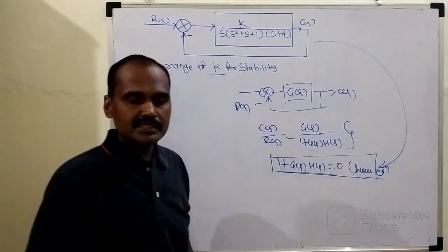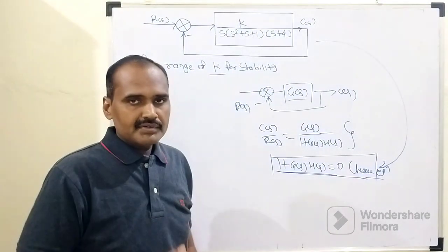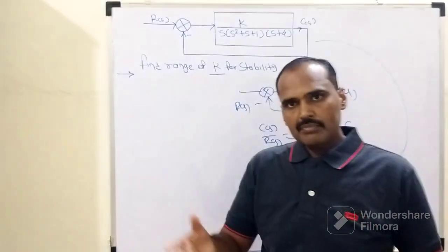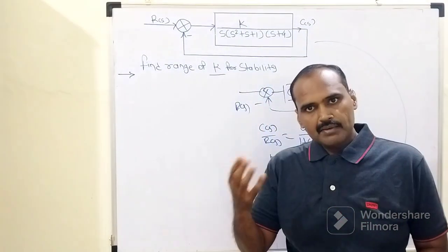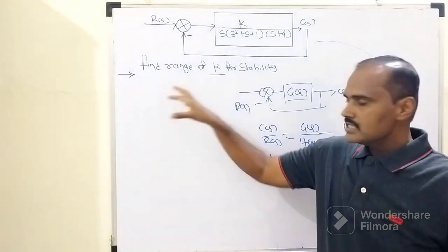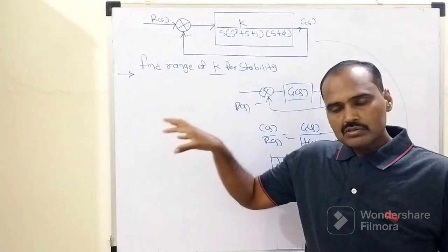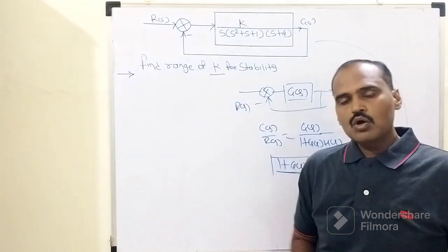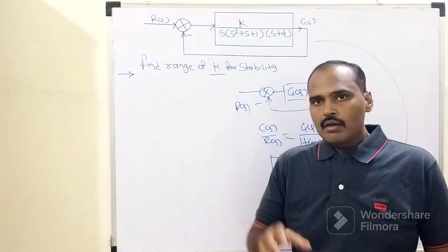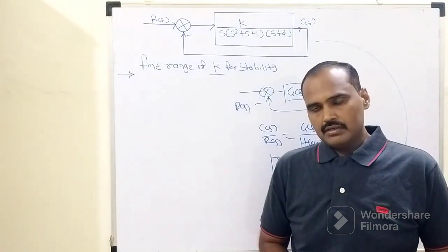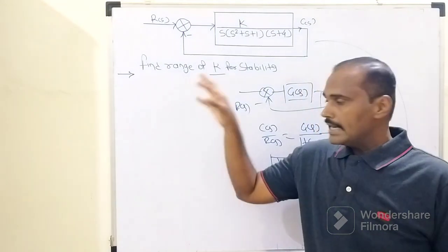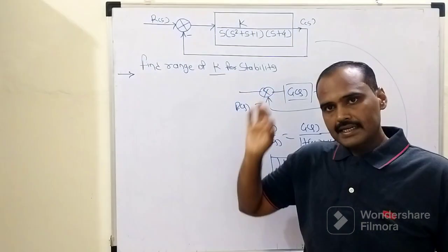Once we have the characteristic equation, according to the basic theory of the Routh stability criteria, its different coefficients are arranged within the Routh array. This is the basic strategy of the Routh criteria: each time we declare a Routh array for the characteristic equation, whose elements are the coefficients lying at even and odd positions within that characteristic equation.